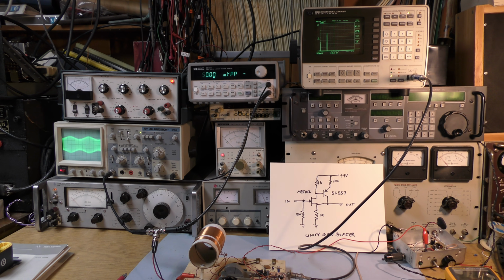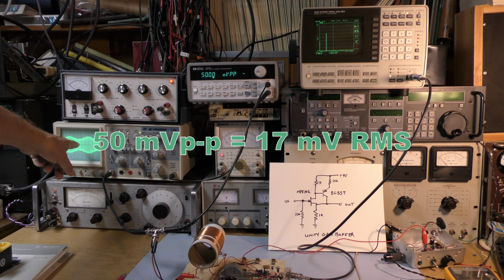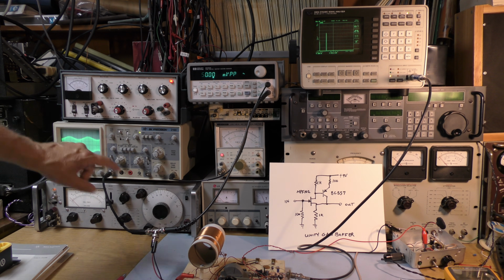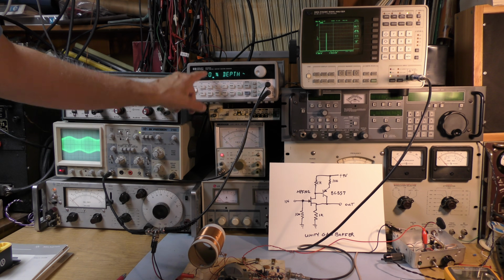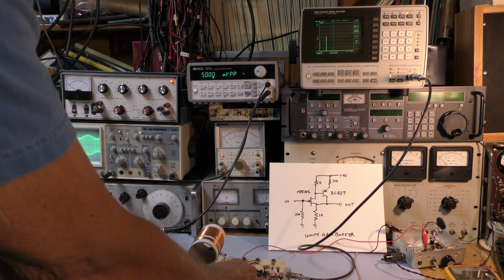Okay, I've created a modulated signal with 50 millivolts peak to peak. 50 millivolts peak to peak is certainly in the square law region of the diode. Looks to be about 20% modulation. Let's check it. 20% depth. So a 0.2 index on the modulation. I had to make the screen more sensitive, so the full scale is sitting at minus 70 dBV instead of minus 20 dBV. We can tune the crystal radio